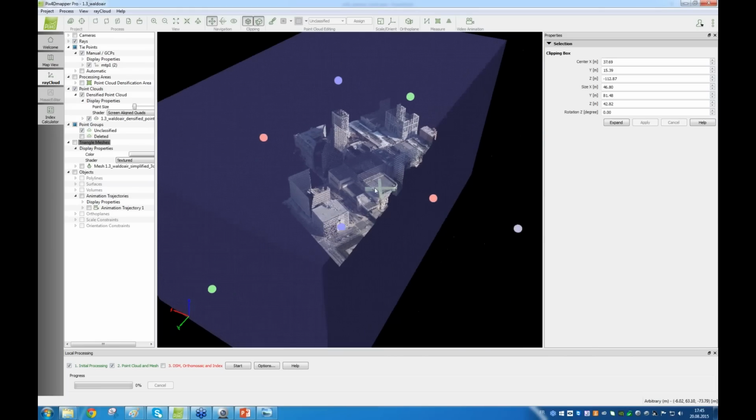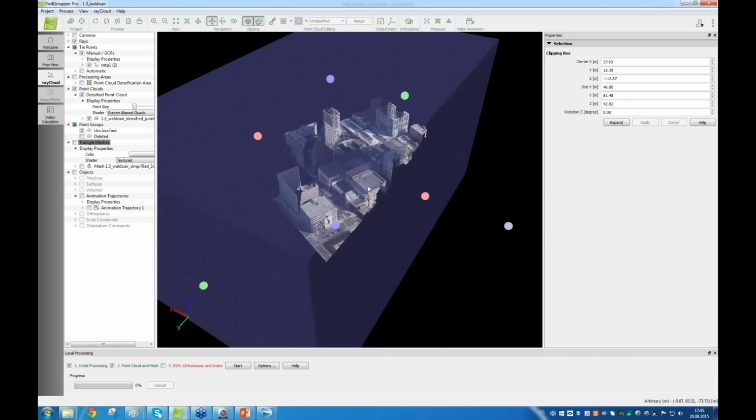If you need a better cross profiling tool, some that we suggest on our website: if you're working mostly in 2.5D, Global Mapper or Quantum GIS are good tools that provide a nice section and profile tool. And in terms of point cloud, the Bentley software called Point Tools is also a nice option to perform cross sections and so on.